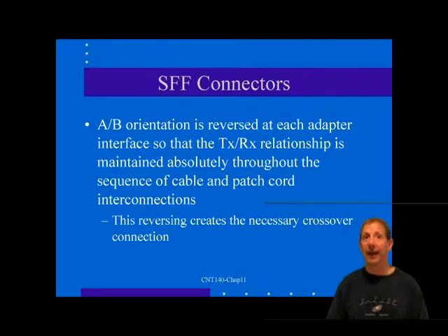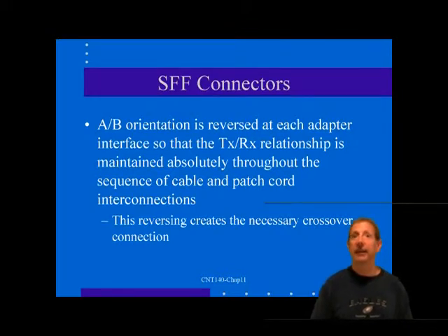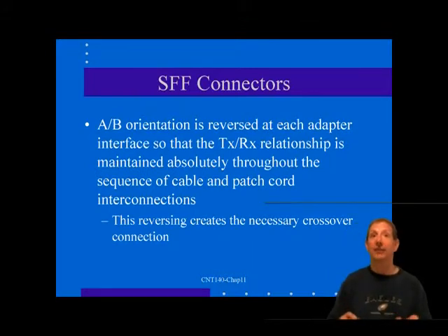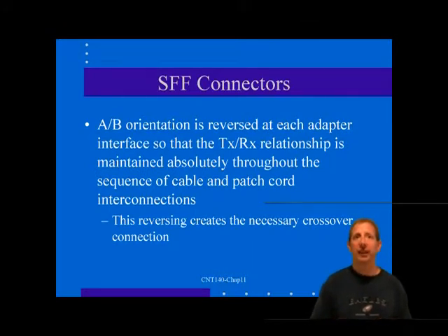The SC connectors and adapters must be oriented in a particular manner to preserve this relationship, and they are still often used to illustrate the arrangement. The SFF connectors automatically orient themselves because each fiber is permanently placed in its location in the connector. However, this does make pair reversals harder to remedy, as one cannot simply unclip and reverse the SCs.